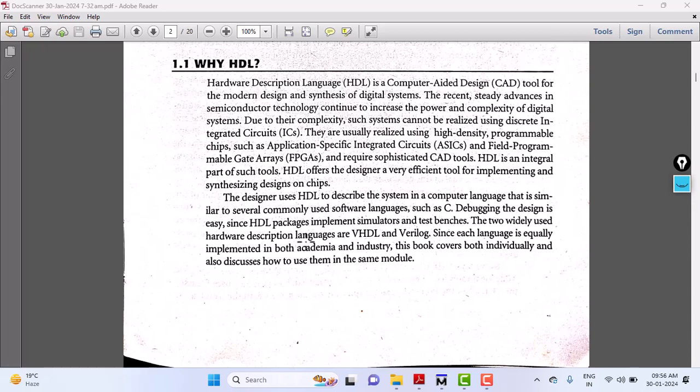What is a test bench? See, when you develop an AND gate or OR gate, maybe the AND gate you can test because it has only 2 inputs. You will have 4 possibilities. Manually, you can do the testing. What if I give you a logic circuit with say 100 inputs? How many possibilities? 2 to the power of 100. Can you manually do 2 to the power of 100 testing? First of all, writing all possible inputs, 2 to the power of 100 possibilities, itself is very difficult. Then how do you test every input and ensure that your design works properly?